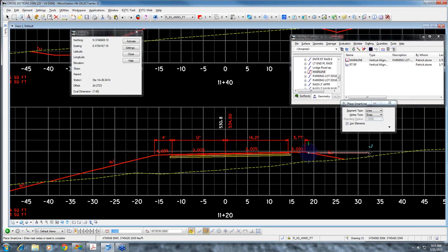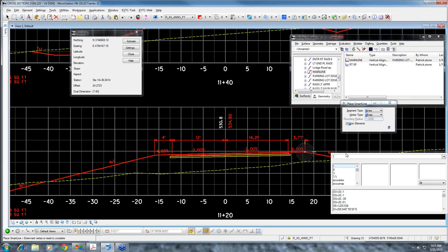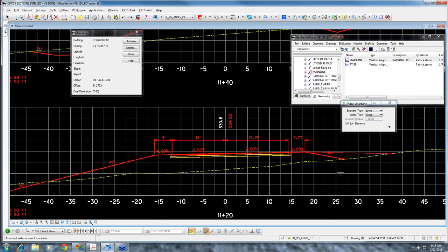So let's go in here and do a distance grade. Let's actually snap to the corner. So if we were going to go distance grade 20, -2%, the same key-ins would apply: the decimal, the percent, the slope, the fractions. You can enter all that in there.